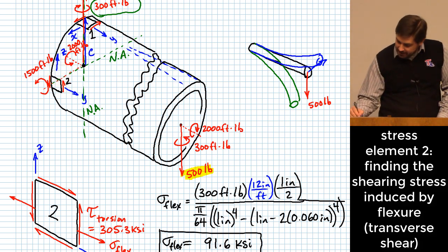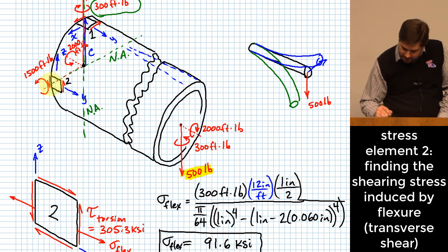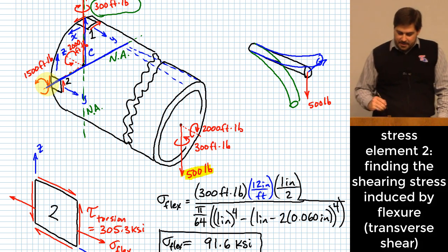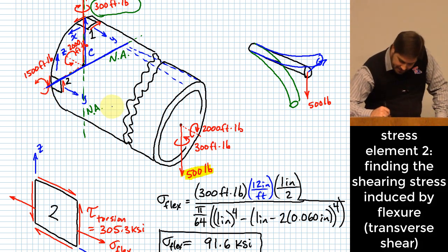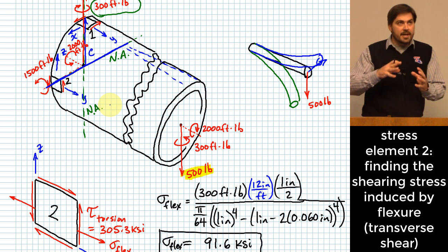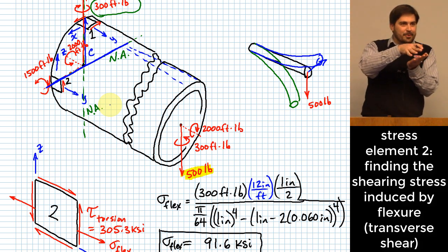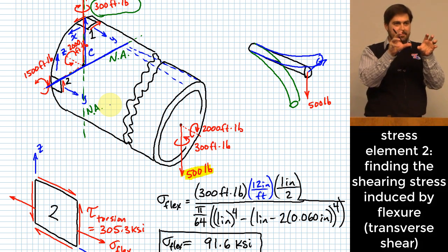And where that cut needs to be made is basically right where this center line goes through right here. Okay? And the reason we're taking that as the location where we are cutting it is that essentially our worst case scenario for this phone book effect that I was just talking about, where the pages want to slide relative to each other as the phone book bends, right?